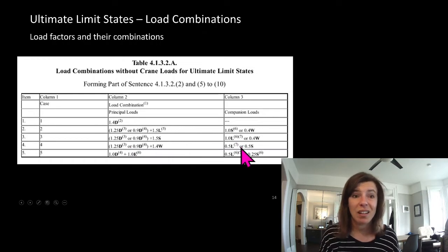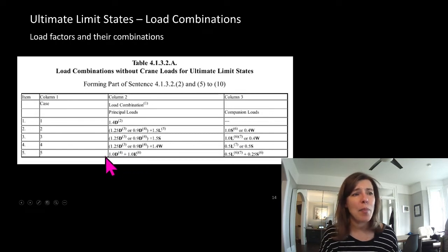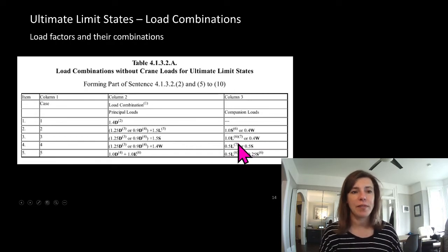We're starting to get a lot of load combinations there. And then seismic, we don't multiply it up for anything here. We have dead plus our seismic, and then we could have 0.5 live plus 0.25 snow. Now, all of these, though, there's a possibility that these actually improve our load case. Again, not very often, but we would have to think about that too.